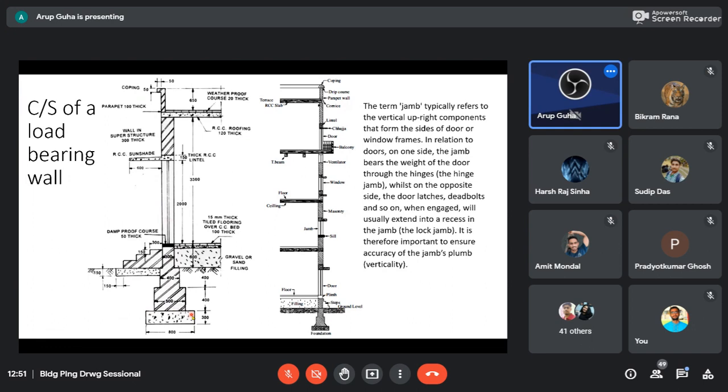So we flare up the foundation so that the pressure is distributed. Means if here you have a weight W, that is being divided by this width, so the pressure reduces. Instead of say 10 inches over here, or rather 250 millimeters, here it is 800. Naturally, the pressure is reduced and the soil can take that.